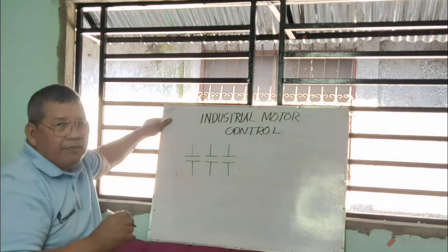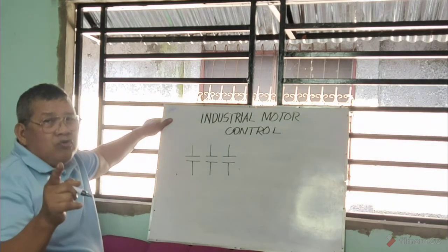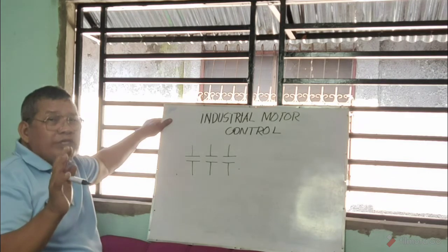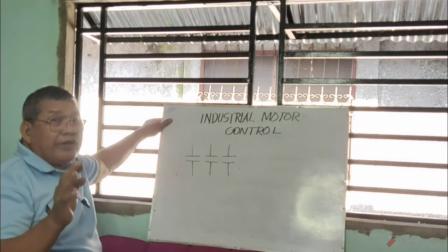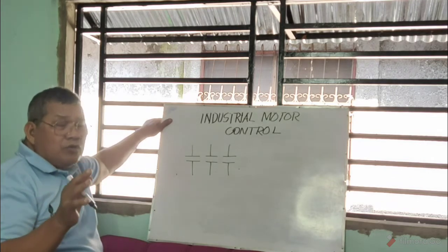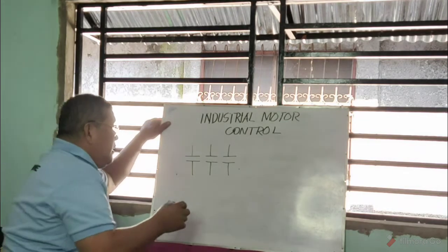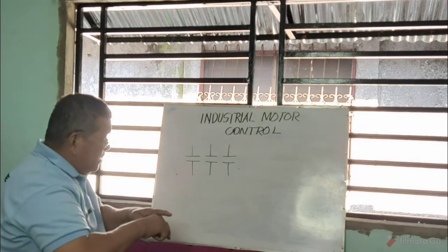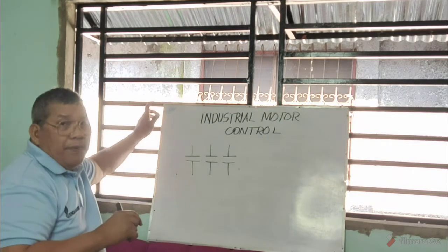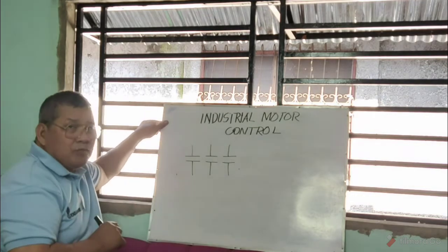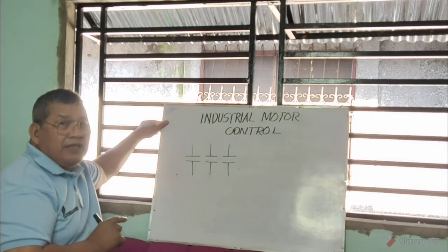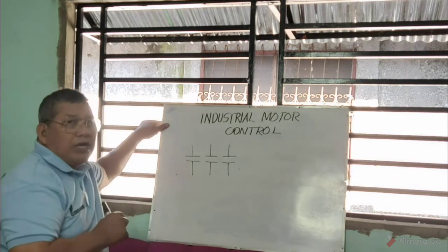Okay, now remember, there are no main contacts that are normally closed. So when we say normally closed, all are auxiliary contacts. But there are also open contacts that are considered auxiliary contacts. So these are the main contacts. Now remember, the symbol is an open contact, normally open contact. But how would you identify if this is a main contact or an auxiliary contact?